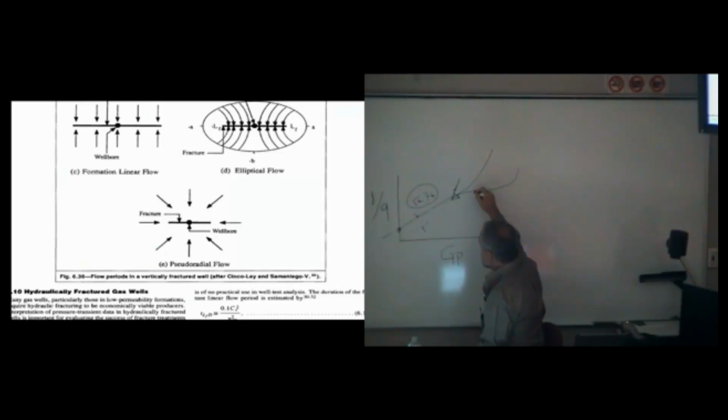I've got 40 years of professional history. I have never, ever seen a well break east rather than north. Never. Vertical fractures, it's easy to explain in multi-frac horizontals in a pattern. There's no place for radial flow to exist.